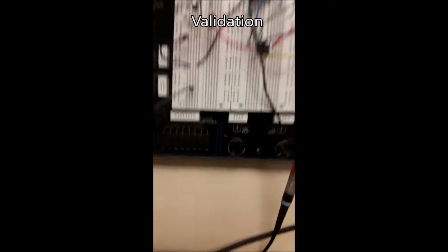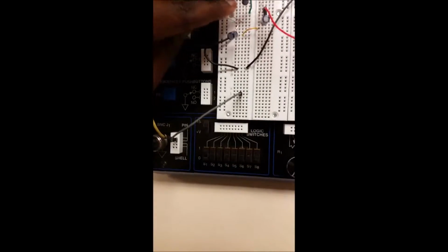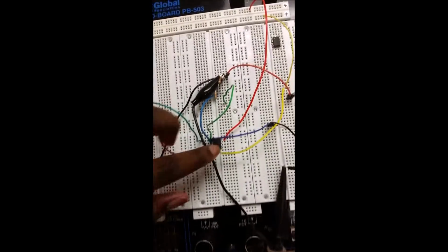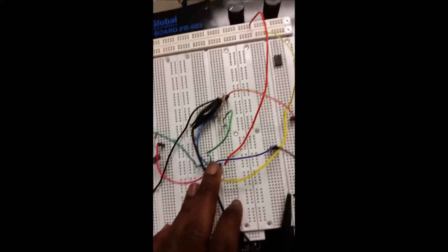So right here we have our circuit, which is a third order low pass Butterworth filter. We have the input from the function generator coming in here and going into the 3 resistors and capacitors and to the op amp. And we also have the R1 and R2 over here, which does the amplification.